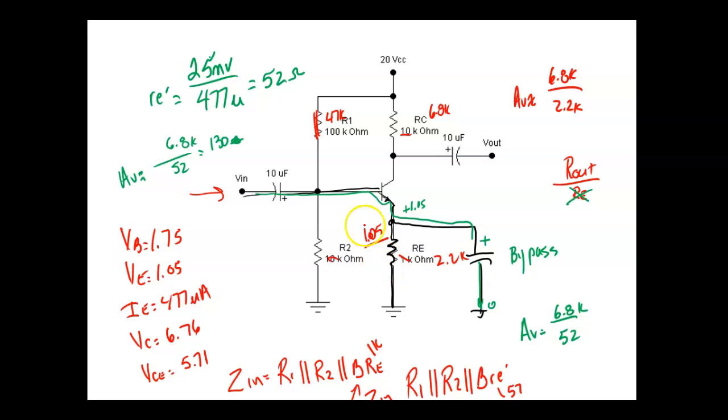But what we can do is once we establish the beta, temperature can't change it, but the AC signal can change it, which is really neat. So RE, that's your temperature stabilizing resistor right there. That's the function of that resistor in life, is to keep beta from changing with temperature. It's pretty cool. Okay, so I bypassed it. We got a gain of 80. We figured it was going to be around 130, but we got a gain of 80. Well, 85, right?